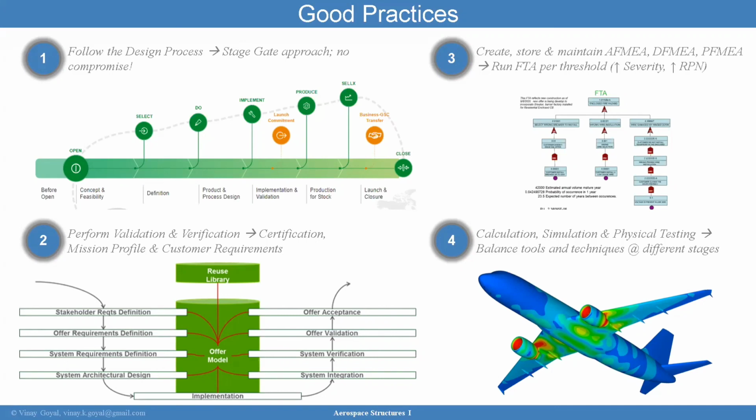The other very strong tool that helps you really avoid, or mitigate at least as much as possible, is the FMEAs, right? This documentation that you put together where you really brainstorm and think about every single thing that can go wrong. You assign values to the different parameters. Again,